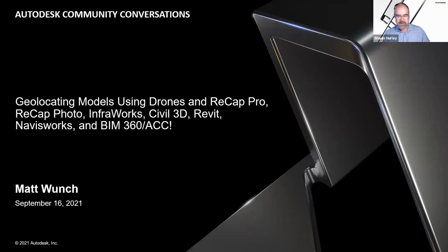This image overlap is great because if you have some shots that for whatever reason, maybe the camera was out of focus or too much reflectivity based on water or glass or something like that, and the model just doesn't quite look right, you can get a good idea of what's going on with some of the overlap here in the elevation model as well. There's information about those ground control points that we saw earlier. So a nice little overview of what your project contains.